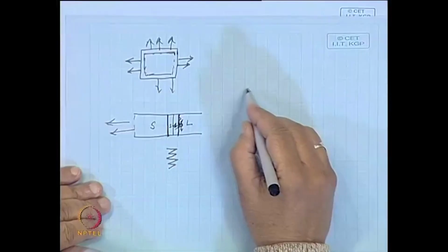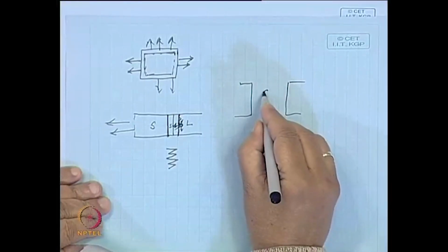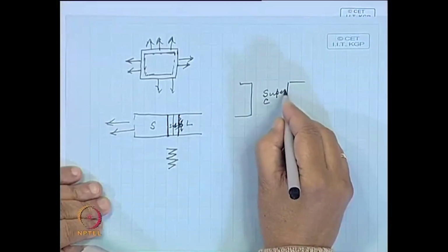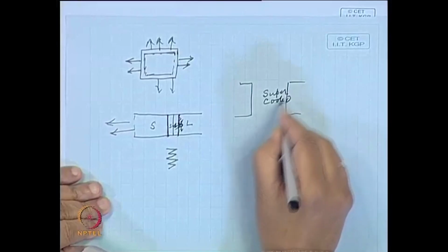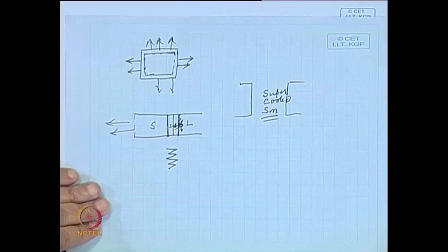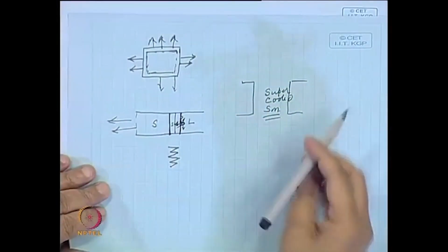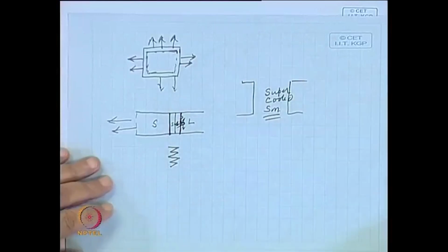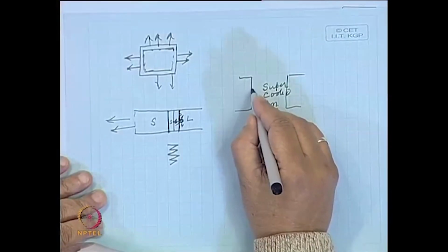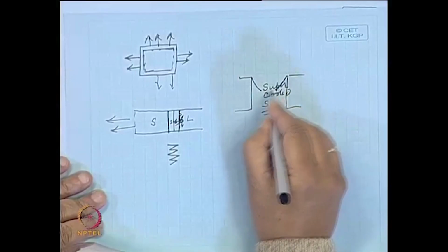You can visualize, suppose in a mold, you take a mold and you have supercooled, let us say, tin. For solidification, it is necessary to have some amount of supercooling. This is supercooled. In this case, it is possible to maintain a negative temperature gradient. When you pull it and solidification starts, the temperature goes up. So, here you will have the temperature maybe like this.